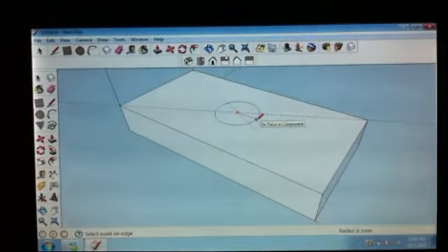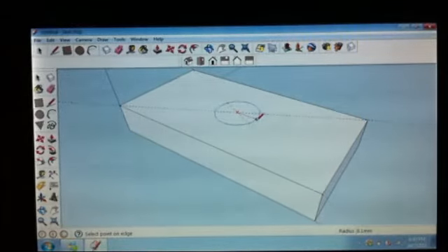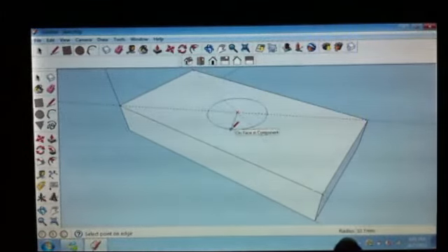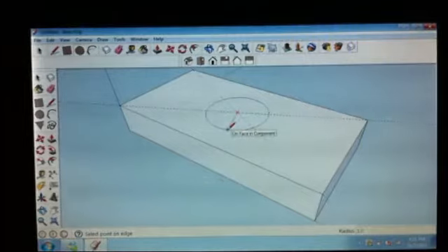Now you're going to get the circle to drill the hole. You still remember what hole size you need: for a 3 mm rod, you use 2.5 mm. But in this case, because it's a computer aided drawing, after you hammer the rod through, the hole will still be 3 mm. Here you're looking at radius, you see below here. So a 3 mm diameter means 1.5 mm radius. You enter, and now you get that hole formed.